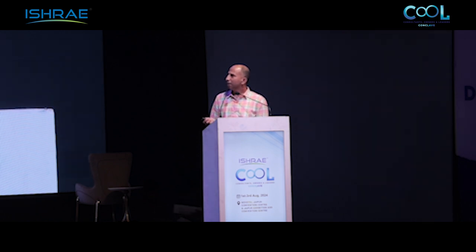Now, some of the widely available not-in-kind technologies which have a lower operational life cycle cost than vapor compression include the absorption or adsorption fired by geothermal energy. It has a lower life cycle cost. Most of these technologies have a higher capex, but their operational cost is much lower than traditional vapor compression technologies, and overall on a life cycle basis they will be much more economical.